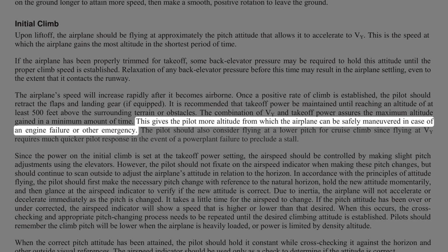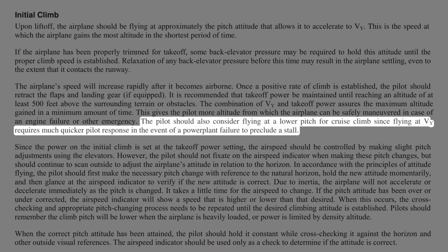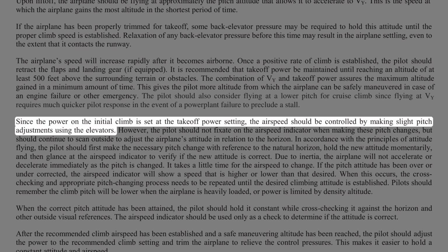This gives the pilot more altitude from which the airplane can be safely maneuvered in case of an engine failure or other emergency. The pilot should also consider flying at a lower pitch for cruise climbs since flying at Vy requires much quicker pilot response in the event of a power plant failure to preclude a stall. Since the power on the initial climb is set at the takeoff power setting, the airspeed should be controlled by making slight pitch adjustments using the elevators.